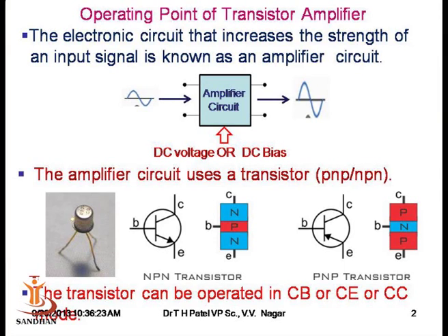When a transistor is operated as an amplifier, there are basically three kinds of circuit connections possible. If we keep one of the terminals common, then the other two terminals make either a common emitter amplifier circuit, or a common base or common collector circuit. In amplifier circuits, most of the time the common emitter circuit is preferred. It has many advantages. Okay, what is the operating point then?